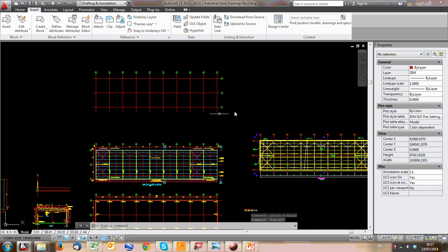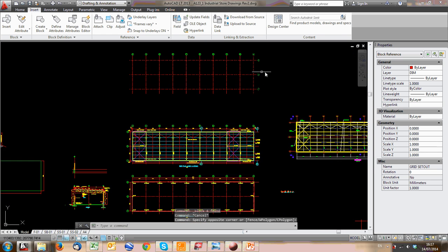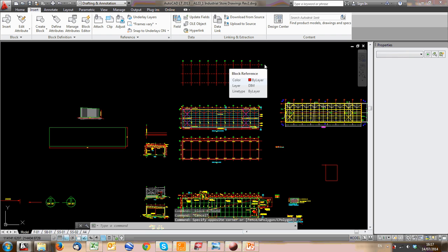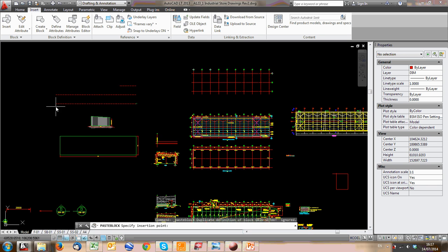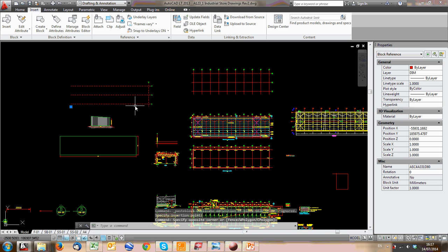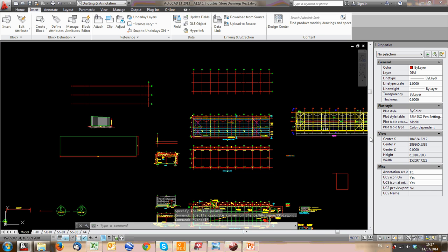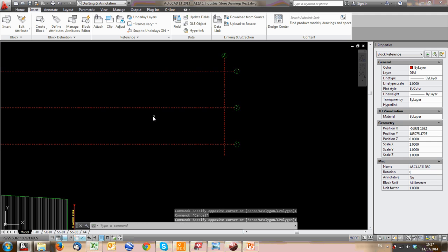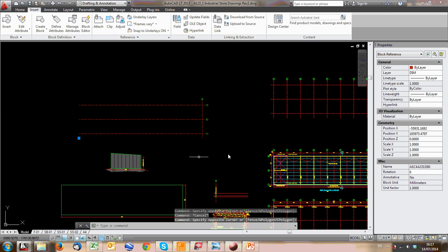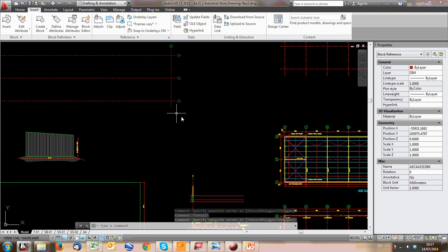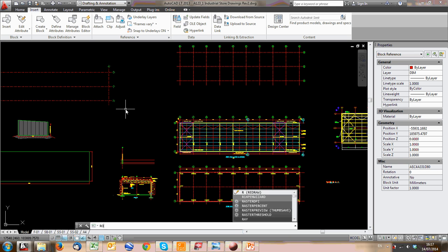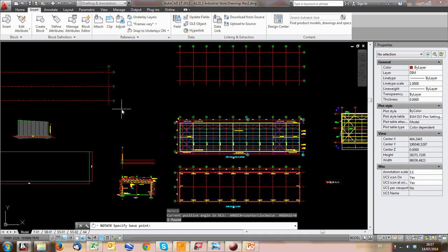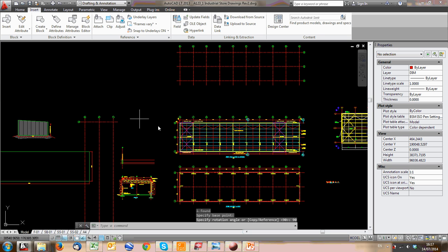The easiest way otherwise to create a block: you select all of this, you copy with Control C, then Control Shift V, and it pastes it there. What I've just done is create a block. This block now, this sees it as one unit. And the reason that is useful is that I can just click and drag this around quite easily to create the rest of my drawing. So I rotate, RO, enter, turn it 90 degrees.